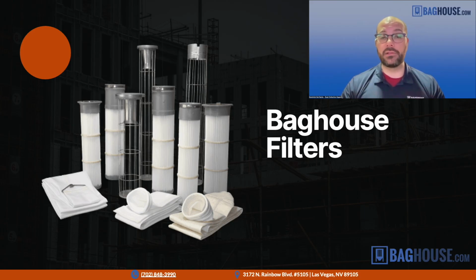Now, in certain spots, you might have a mix of chemicals, moisture, humidity, different things going on where you can have acid reactions. Now, in these cases, we might use a different medium that's especially resistant to those kinds of chemicals, things like acrylic bags, or maybe bags made out of PTFE felt.